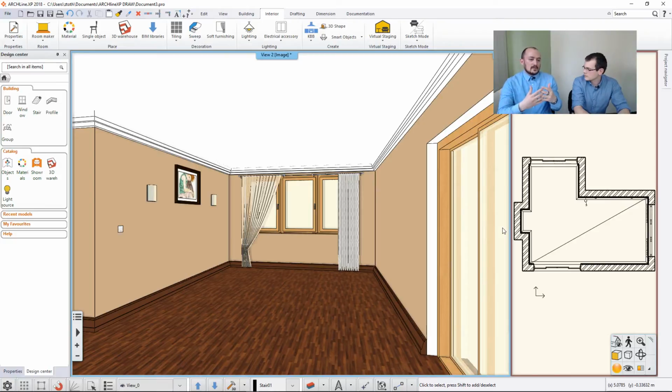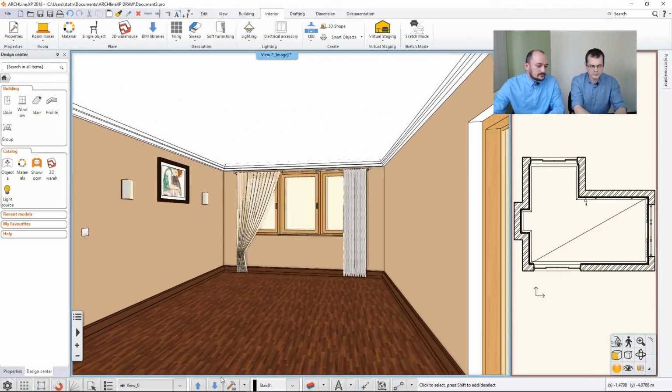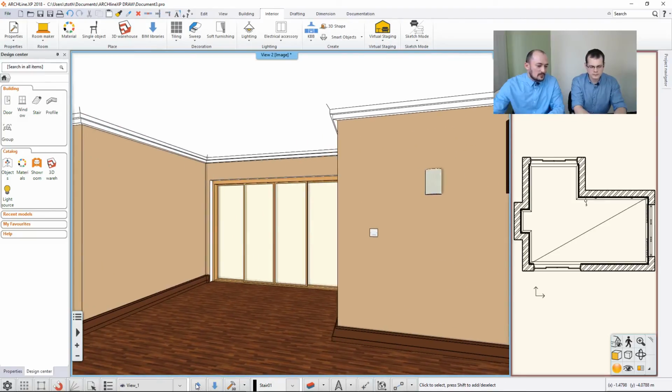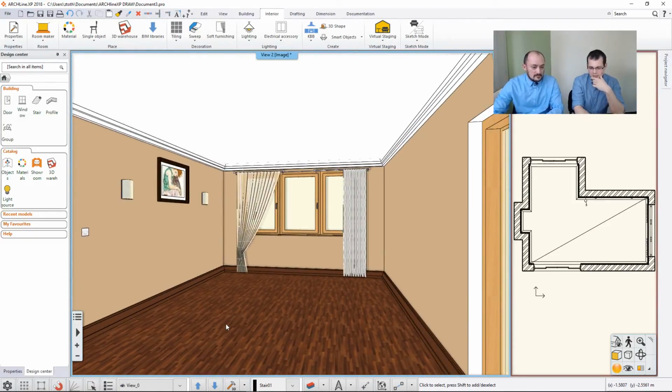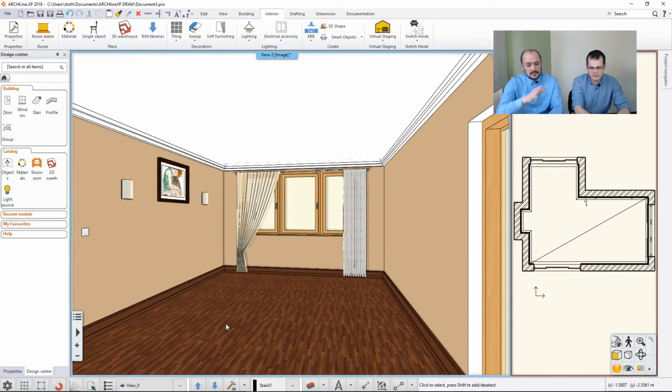So even when I'm working with an intermediate size model, I just quickly set up several views, and I think it's a useful trick to know. With this one, you can navigate from one view to another. See, I'm just jumping from one view to another. It's easier that way. This is based on that setting that I already created. I also know that the Page Up, Page Down keys would do the same trick. On your keyboard, you all have a Page Up and a Page Down button, and that's doing the same. Page Up is going to the next, Page Down going to the previous.